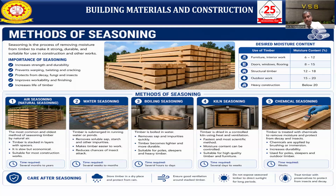Now we need to take care of the seasoned timber. Timber should be stored in dry places and protected from the rain. We should not keep it in the open atmosphere, otherwise it will be damaged by rain and other things. Ensure good ventilation around the stock of timber. Do not expose the seasoned timber to direct sunlight for a long period, due to rapid drying. Treat the timber with a preservative to protect it from insects and decay.